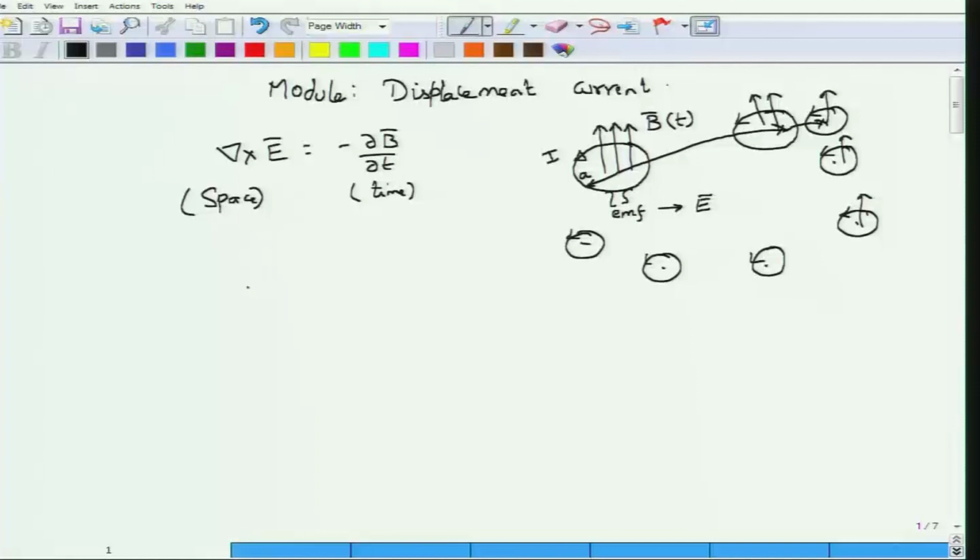Am I looking at some sort of relation which would tell me that there is a quantity which we can call magnetomotive force, just as you had a quantity called electromotive force, which was the line integral of electric field between any 2 points. You can similarly talk about H dot dl and call this magnetomotive force, okay, in analogy with the electromotive force. So the question that we are asking is, will there be any MMF induced if there is a change in electric flux density, right.